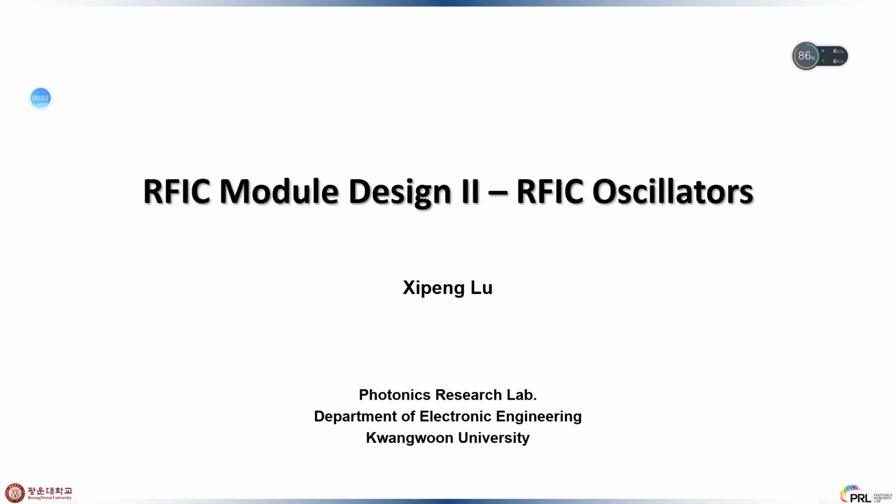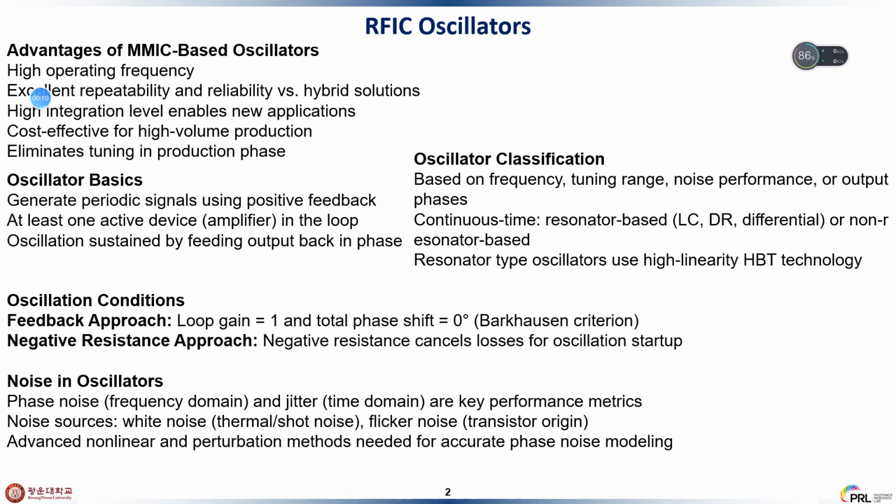Hello, today my topic is about the RFIC module design tool, and it's the oscillators. So the first part is the introduction of the oscillators, and it's the advantages of the MMIC-based oscillators. It has high operating frequency and excellent repeatability and reliability, and it also has hybrid solutions. High integration level enables new applications and is cost effective for high volume production, and it eliminates tuning in the production phase.